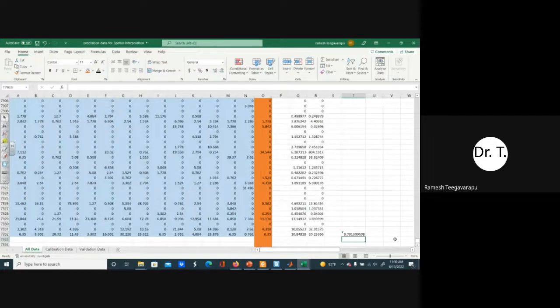0.8. So that indicates that my values, which I'm trying to estimate for the daily precipitation data, which I'm assuming them to be missing, and I'm using an optimization approach to estimate missing values, I'm doing reasonably well for a simple linear regression model. Okay, instead of using inverse distance method, which may not work out very well, I'm using some kind of an optimization approach.